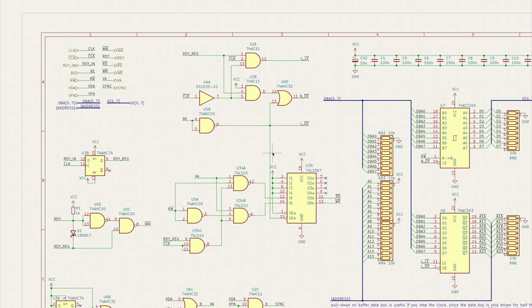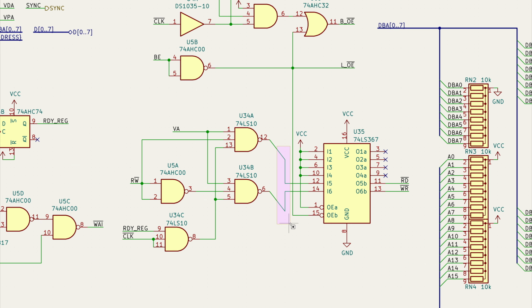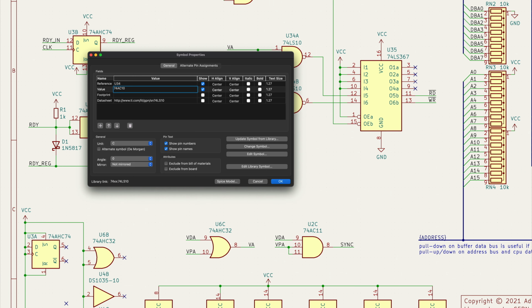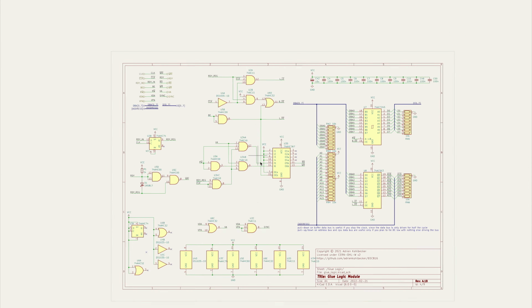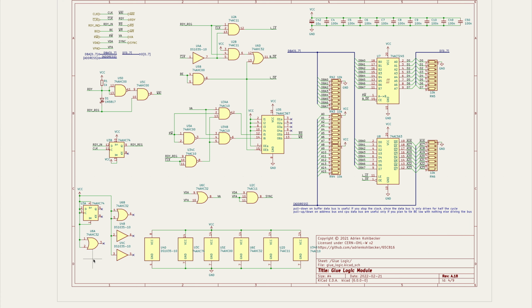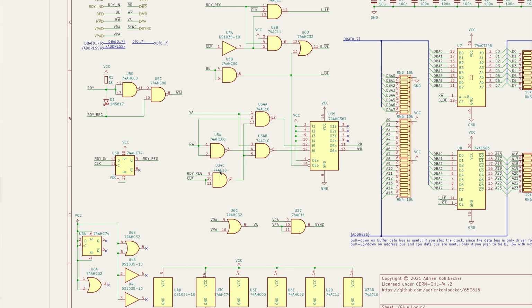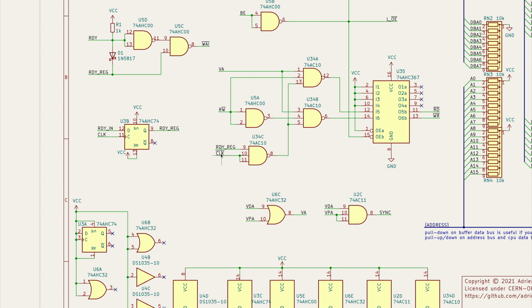And there we go. So I was able to use the spare 74AC10 in order to do the NAND with the clock, and this one is even a bit faster, so that's good.